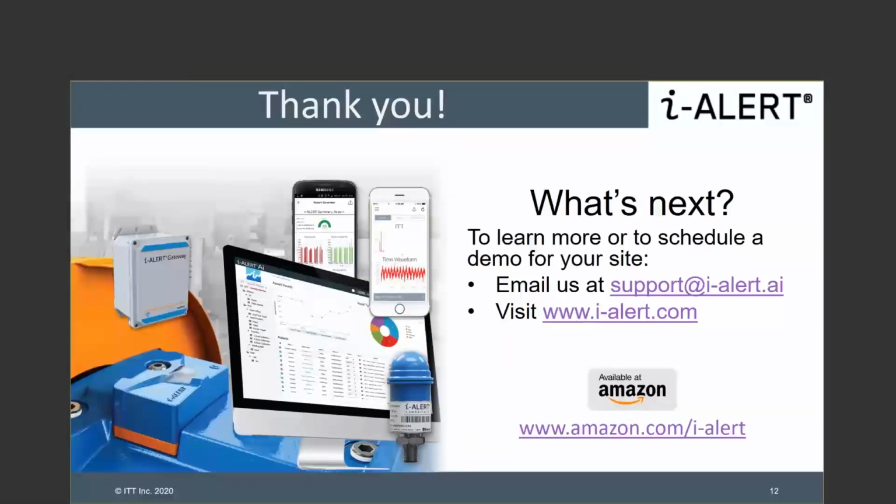All right. Thanks, Dave. There's a question on classifications. How do we handle Div 1 or Div 2 hazardous areas in refineries? Well, specifically, the iAlert is Class 1 Div 1 rated. We have a gateway that is Class 1 Div 2 rated. In a refinery or another installation, the gateway has to be placed outside of the restricted, hazardous area. Typical range from a gateway to an iAlert is 250 feet line of sight, so that's usually feasible to do. All right.